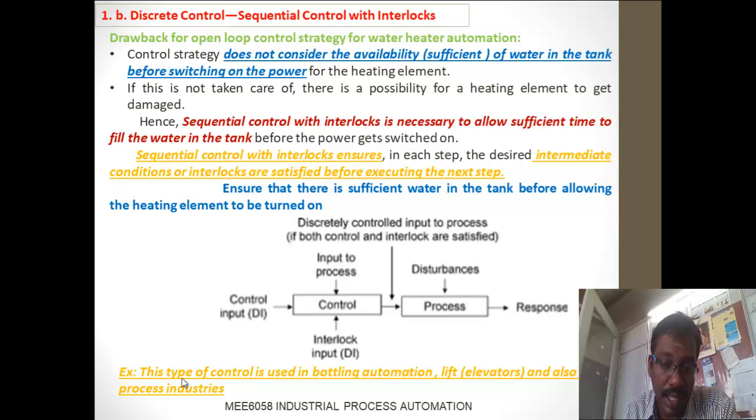These are sequential processes. For each and every process, we have a single controller, and each process is executed with respect to the controller. The controller checks whether the process happened properly or not. If the process did not happen, the controller will not execute the next process. Since it is not a continuous process, it's a discrete process, with step-by-step sequential control. Sequential control means each and every process is checked properly, and if any process in the system has not happened properly, the sequential control will not allow us to execute the remaining processes.